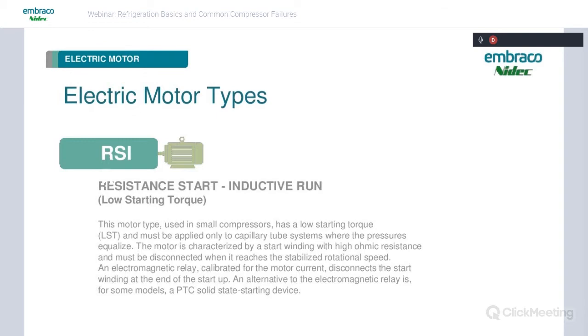Sorry for the missing R there, but that means resistive start, inductive run. Basically, what this means is you have no capacitors, no start capacitor, no run capacitor on this type of motor. It's a very simple motor used in small systems that use fixed orifices like capillary tubes. So it's a low starting torque motor by design. And the point here is you have no capacitors on this type of motor.